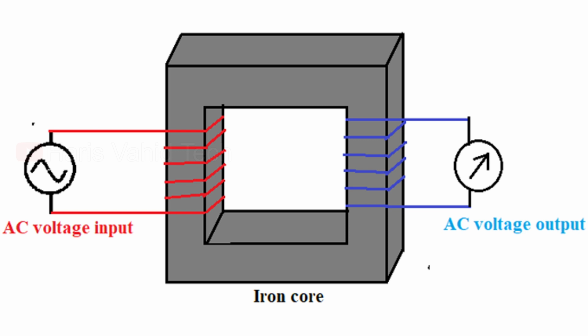As shown in the figure, we can use an iron or ferrite core to reduce the magnetic flux loss during power transmission from one coil to another coil. During this time, the magnetic flux leaked into the atmosphere will be considerably less than when we used the air medium, as a core is a very good conductor of the magnetic field. Once the field is generated by coil 1, it will flow through the iron core reaching coil 2, and because of Faraday's law, coil 2 generates an EMF which will be read by the galvanometer connected across coil 2.